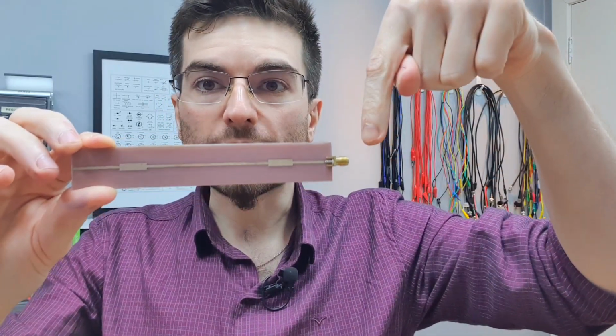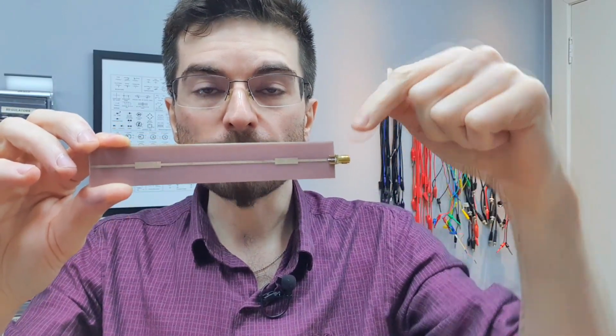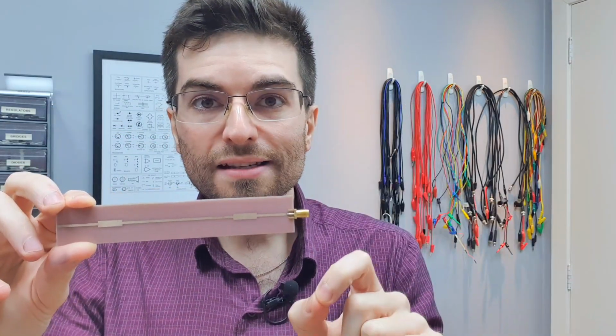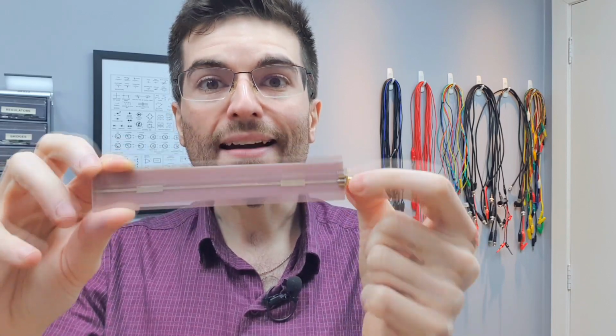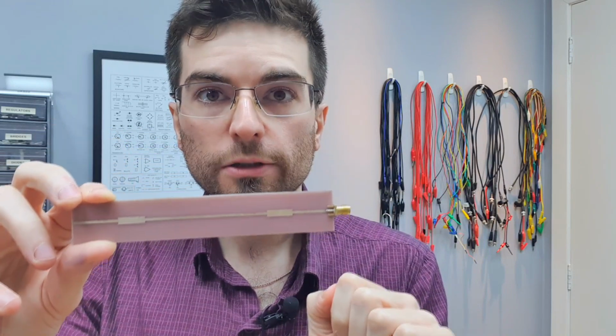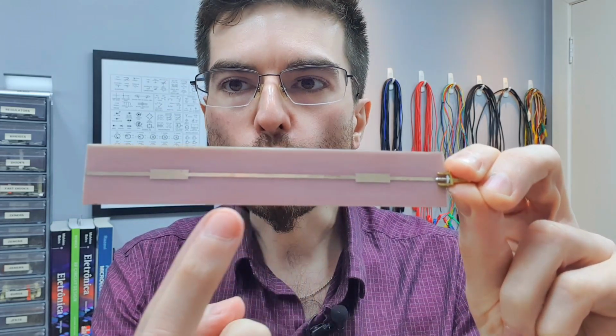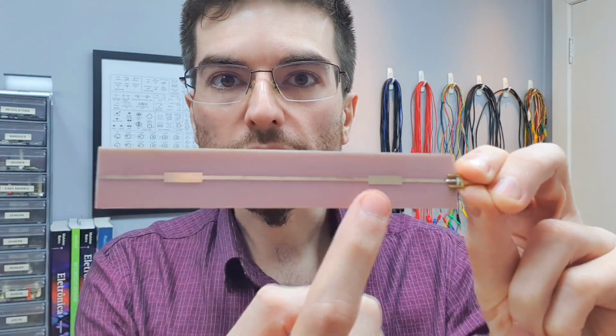So if we put an oscilloscope here on the port and monitor the voltage, we are going to see over time small positive or negative pulses of voltage that are actually the reflected energy arriving at the port. So the main idea is that if we capture the time between two discontinuities, between two pulses on the oscilloscope, as we know the physical length, we can back calculate the electrical length or the effective permittivity.